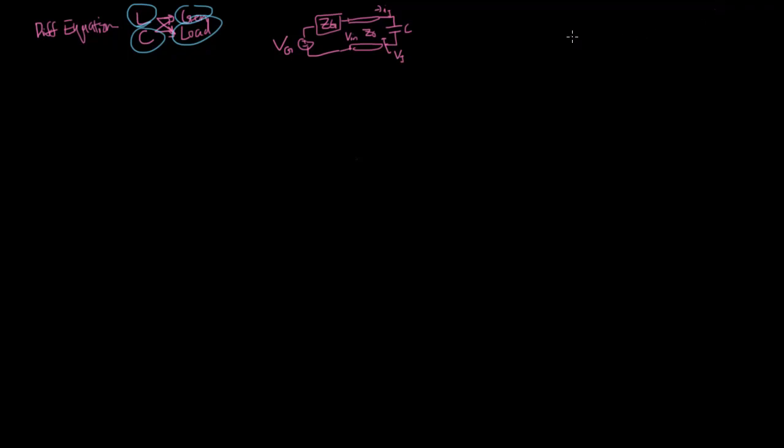Separately, we'll also solve the situation where we have the same generator with its impedance, and we have an inductor before we go into the transmission line. So in this case, the reactive load is on the generator side, and we'll keep this as an open circuit. Characteristic impedance Z0. And in this case, our VJ will be referring to Vin. So IJ in this case goes into the transmission line. VJ is what we've been traditionally referring to as Vin.